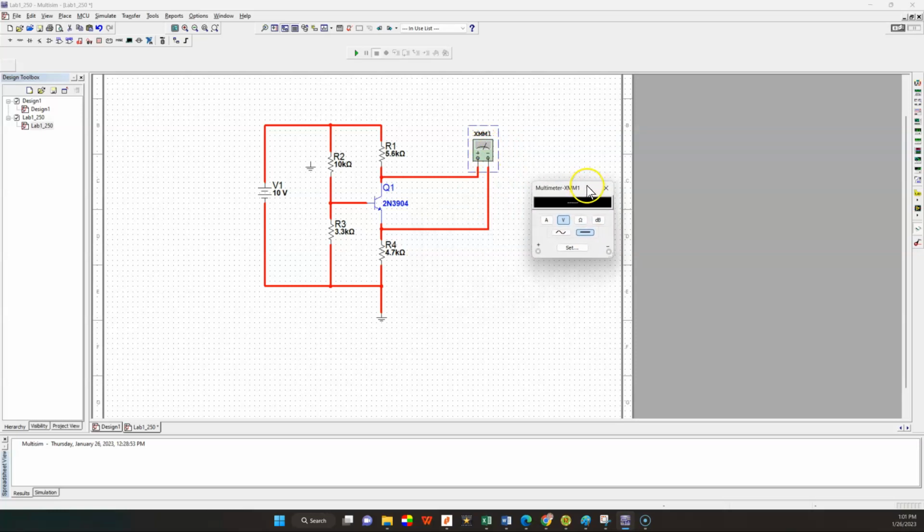And then you switch on your circuit. Then you will get the voltage between the collector and emitter, which is equal 5.99, which is 6 volt. It's exactly what we get in Microcap. But this is how you connect. Well, remember, you have only one voltmeter in the lab, so every time you want to measure something, you disconnect and you connect to measure. So that's the way how we measure VCE.